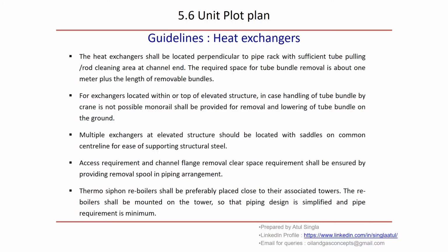Now, for exchangers located on top of an elevated structure. Sometimes we have to locate all the exchangers on some elevated structure. In that case, handling of the tube bundle by crane is not possible. So we provide a monorail arrangement for bundle removal and lowering of the tube bundle to the ground. This is specifically for exchangers which are located at an elevated structure.